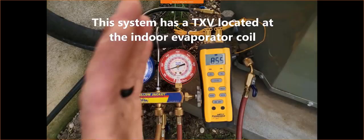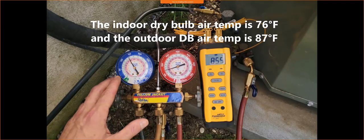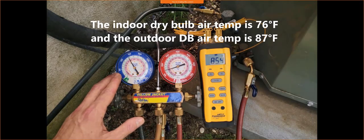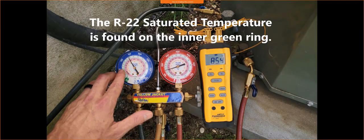So now I'm going to check the refrigerant charge of this R22 outdoor unit, and we're going to let this system run for about 5 to 10 minutes before checking the TXV subcooling. And the thing is, we want to make sure during that 5 to 10 minutes that our R22 saturated temperature is above 32 degrees.